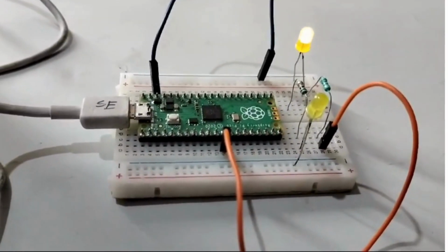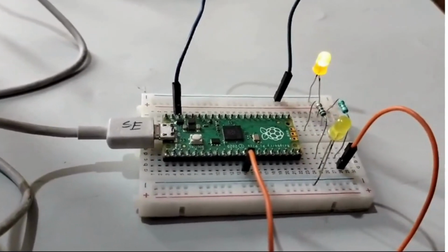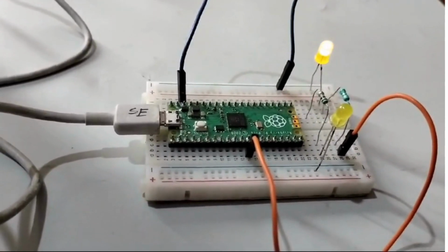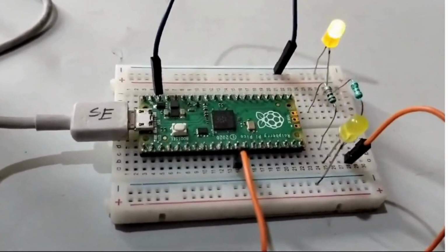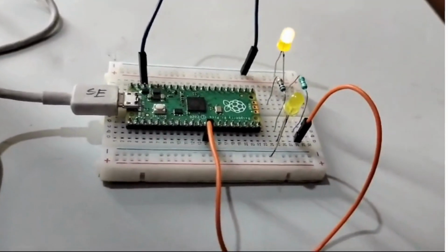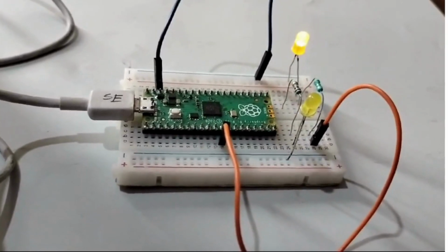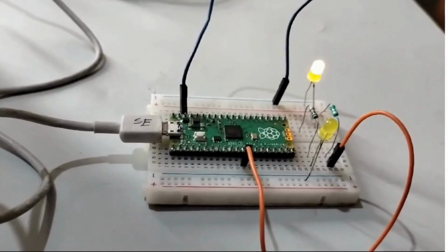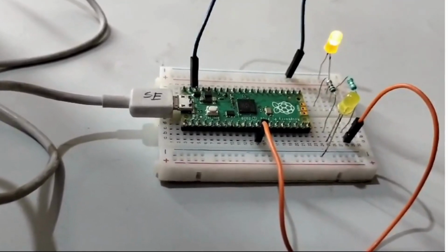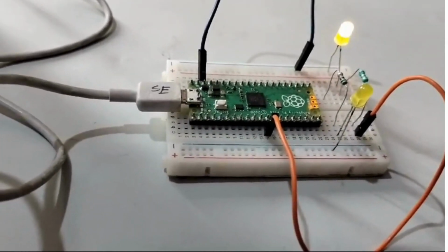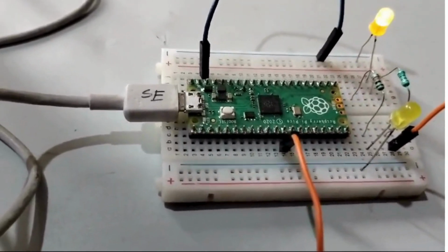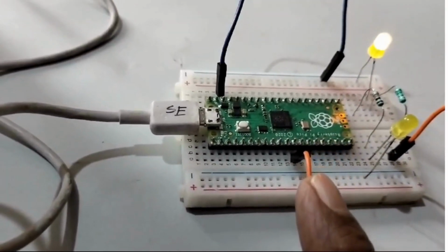All right, friends and students. Now you can see in this video, the same thing is happening. That is, the LED is slowly fading out, and again it's coming back to its original position. But please see here, I have used another board. What board? Raspberry Pi Pico. The program we just saw before is the program which was written in C language. The same program I have dumped onto this particular Pico board, and with the same program my board is working, and I'm getting the same results or output. You can see here again, this is pin number 9, this is GPIO 9.